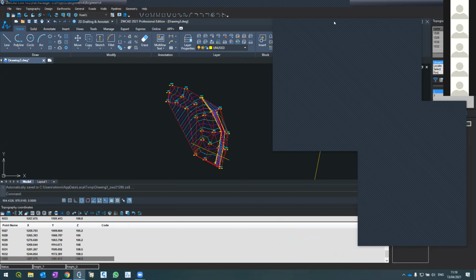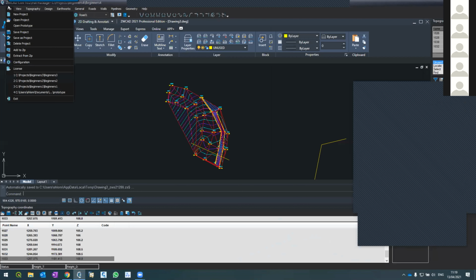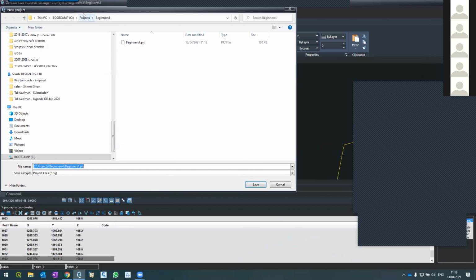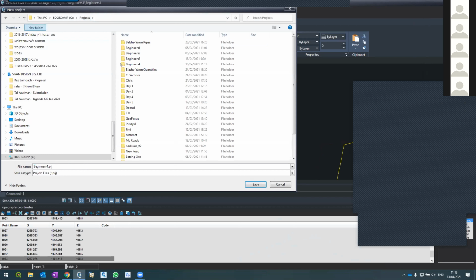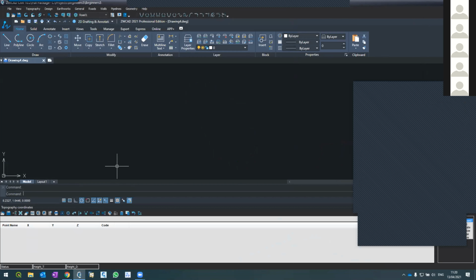Then all of you, please start a new project. You do it by starting your ZWCAD Civil, go to File, New Project. Open a folder for it, like we already did before. I will call it Beginners 5, and Beginners 5. Okay, and open a project. Then go to the lower left corner, press the most left button, load from text file, load from file, press here.